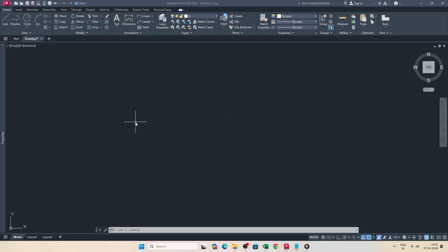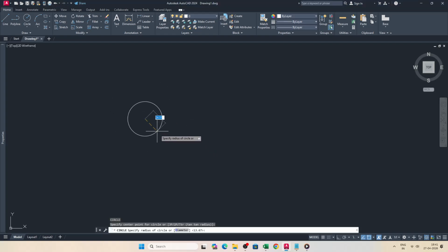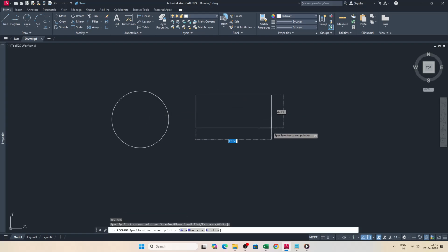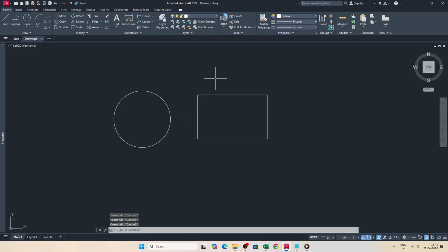In today's video, I am going to teach you how to change transparency of drawings in AutoCAD. Transparency lets you make lines, shapes, and hatches more see-through, so you can emphasize what matters and keep backgrounds visible without deleting anything. You can set transparency for specific objects, or you can apply it across an entire layer. I will walk you through both approaches so you can choose what fits your workflow.